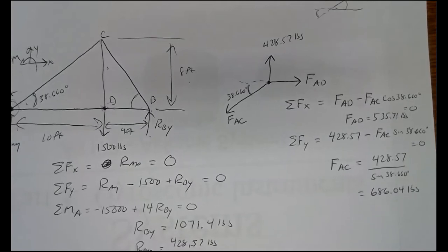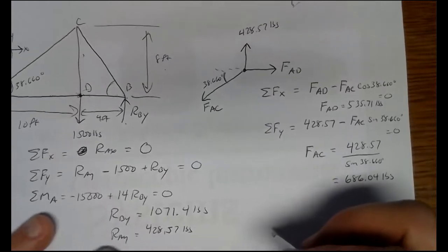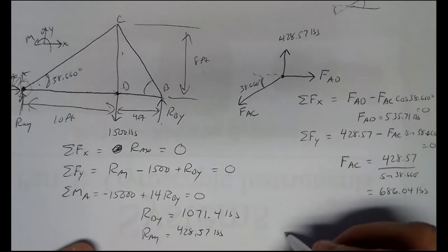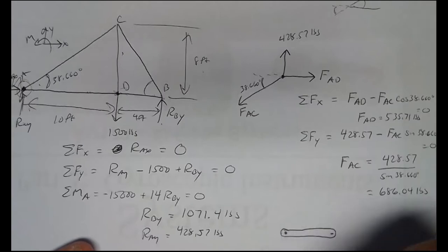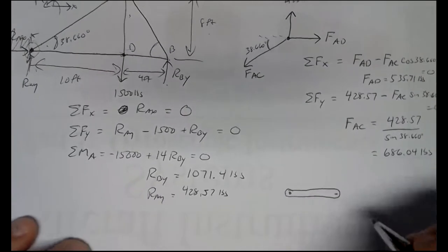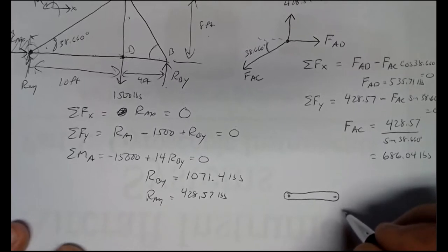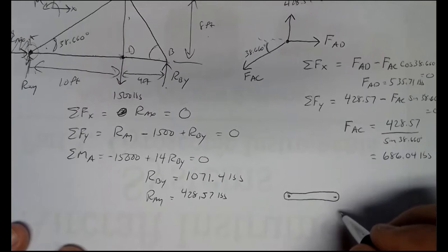Now here's where it gets a little trickier. You have to interpret correctly tension versus compression. So you have to get back into that mindset. I know it's been a little while since we worked on this, but this is a good point to review tension versus compression. So the basic pictures, and something I would probably put on my index card if I was going to be taking this exam. If a member is in tension, then it's been stretched out. And a member in tension will tend to draw its supports back toward each other.